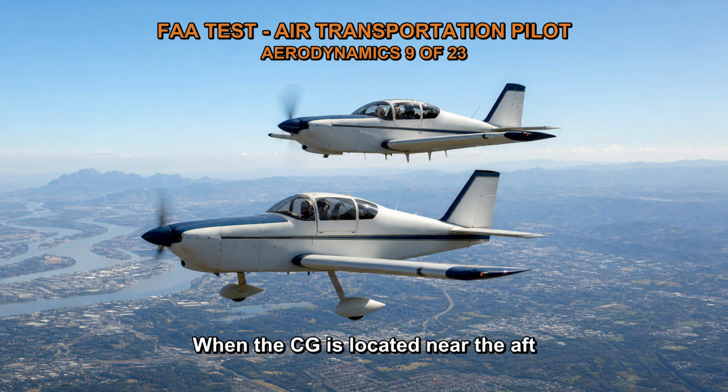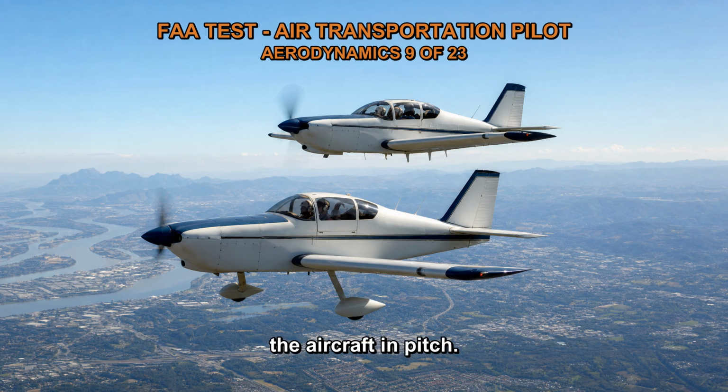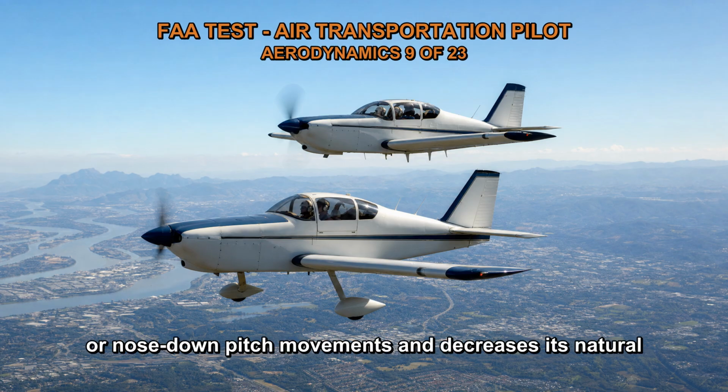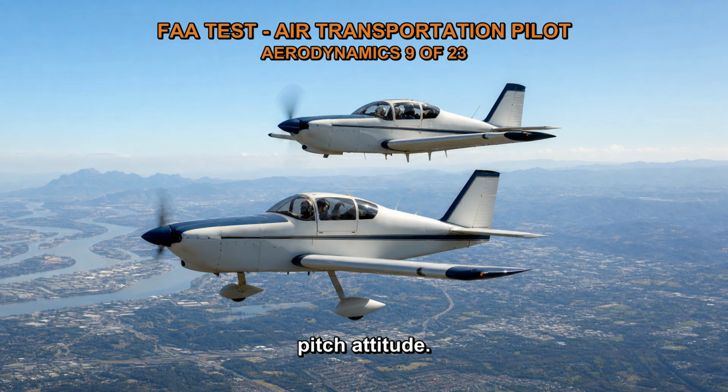When the CG is located near the aft limit, it means that the center of mass is positioned closer to the tail of the aircraft. This configuration tends to reduce the stability of the aircraft in pitch. It makes the aircraft more prone to nose-up or nose-down pitch movements and decreases its natural tendency to return to its trimmed or desired pitch attitude.